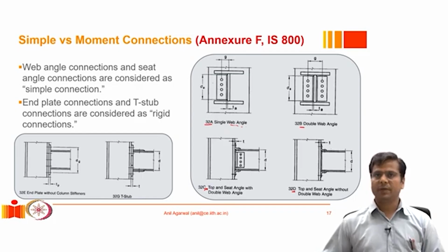A designer should be familiar with what parts can be welded, what parts can be bolted, and what is practical in the field, because a designer may think of having everything welded, but depending on the project's scope and the ability of the manufacturer and the construction company, they have to realize what can be done at the site, what is possible to be erected, and what is not feasible. So all those considerations go into deciding where we can put a bolt and where we should put a weld.